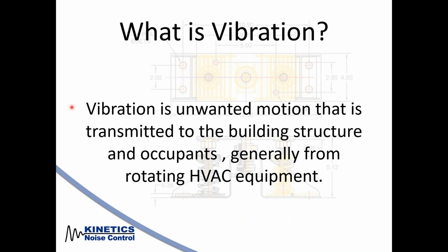Basically, vibration is the unwanted motion that is transmitted to the building structure and the occupants, generally from rotating HVAC equipment. So as human beings, we're actually feeling this vibration from the mechanical equipment, and then our brains are equating that vibration and telling us there's a noise, a buzz.